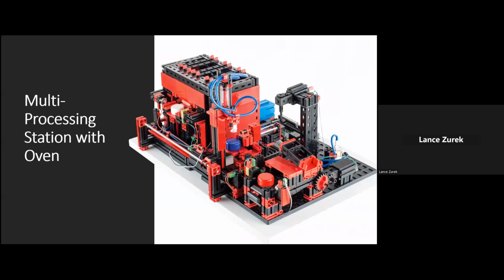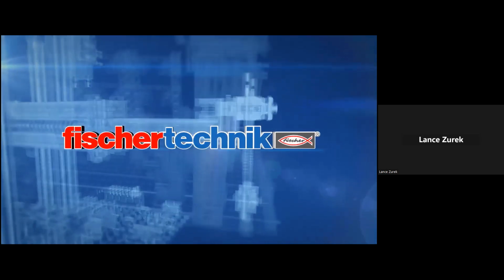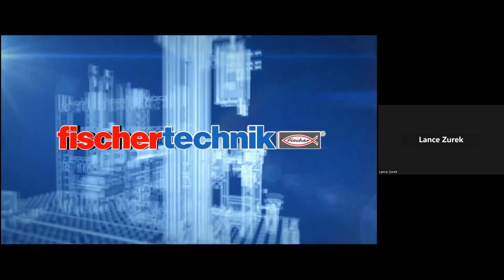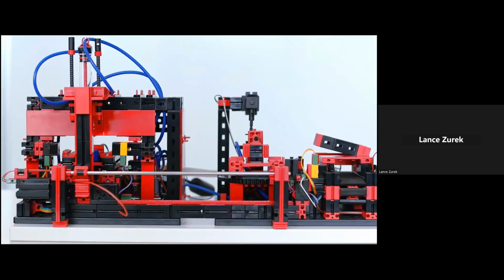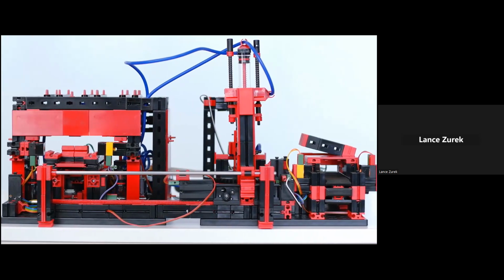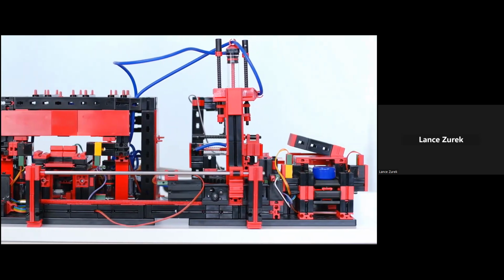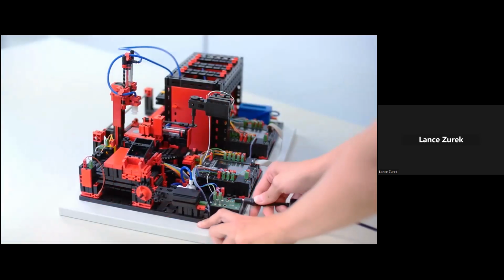The next model in the line is the multi-processing station with oven simulation. Now, this model will feature a furnace simulation with a pneumatic sliding door. There's a downstream processing station with a pneumatic transfer unit that includes a vacuum gripper, a cutter with a rotary table, and a conveyor belt. Components used on this model include 4 mini motors, 6 push-button limit switches, 2 photo transistors, 2 LED light barriers, 4 solenoid valves, and a compressor.